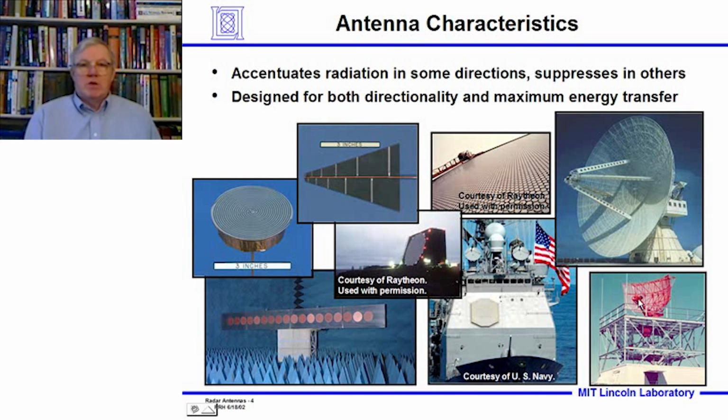In fact, shaping goes on so that this antenna has a very wide beam, wider than the geometrical shape of the antenna would allude to, in elevation than in azimuth. Okay? And we're going to look at a lot of these different kinds. Also, if you look up here slowly, there are two antennas up here, two little parabolic dish antennas that have feeds out at their focus. We're going to get into the properties of all that. That's sort of a big picture introduction I'm giving you of what antennas look like.